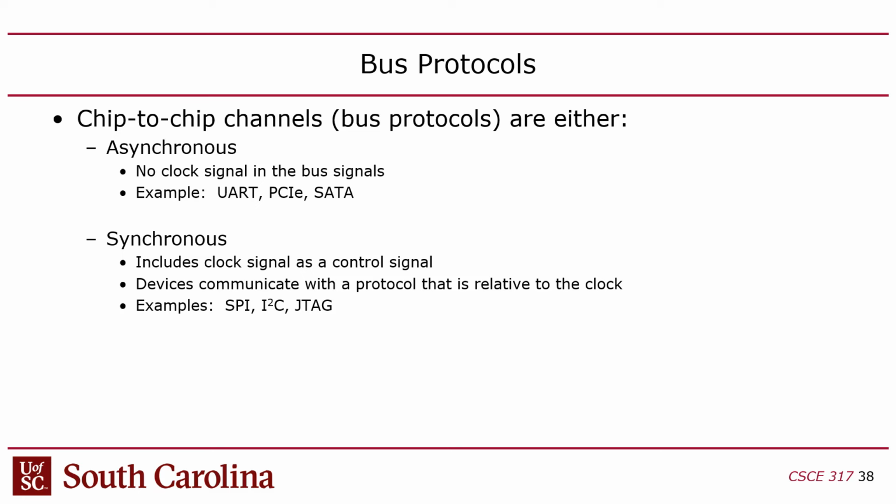But PCI Express is also asynchronous. There's no clock. In that case, the way they handle that is they use 8b/10b encoding, or they use 64b/66b encoding, where they take all the words that they send out and they encode those words with more bits than they actually require. So you have to send 8 bits out, send 10 instead. Use a 10-bit code word to represent 8 bits. And that coding scheme is designed specifically to maximize the number of data transitions inside those code words. Because what you don't want is sending all zeros for a while and then just having a flat line. If you send all zeros on an encoded channel, you're still going to get some flipping in there. That's what the encoding is designed to do.